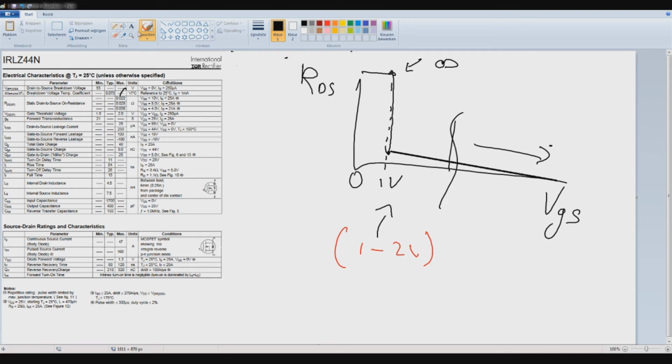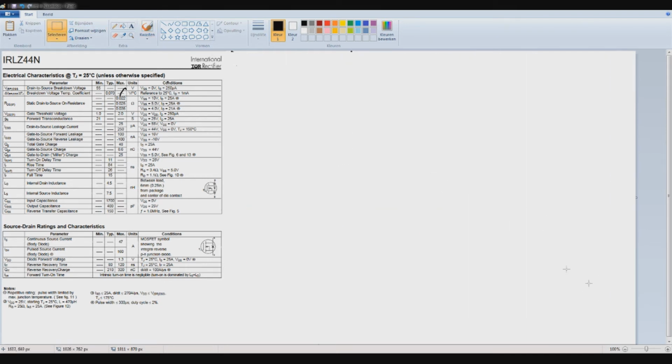And experimentation is also a very good method. And what's next is the gate transconductance, which is not really important. It's basically a parameter which has to do with the gate width and the internal chemistry, and it's not really important to know for switching. Well, drain to source leakage current speaks for itself. It's just the current that gets lost in the internals.